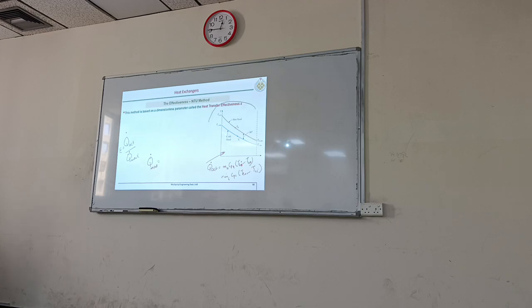Look at this. Again, we are taking the counterflow heat exchanger as our standard or reference. So what is the maximum possible? THI to TCO? The maximum. Yes, yes. If you increase this area, what we can expect is that THO will become equal to TCI.